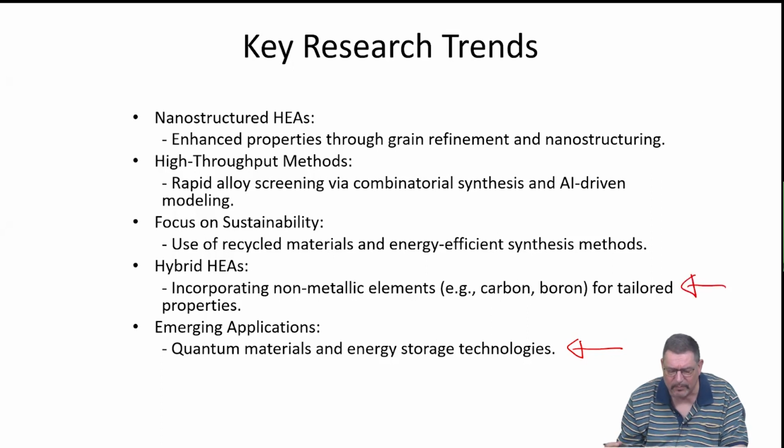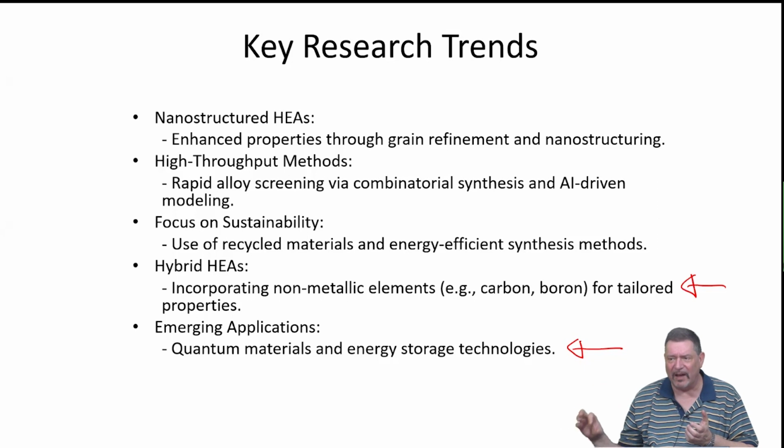This is a nice concept, hybrid high entropy alloys. I would say hybrid CCAs. So people are now thinking of making structural materials which can be applied by getting rid of expensive or very heavy constituents, taking a two-phase approach, going to CCAs, having two-phase materials, and add, for example, interstitial doping, like carbon as in steel, right? And so you can then much more fine-tune whether the carbon goes into interstitial sites of phase 1 or only of phase 2 or both.